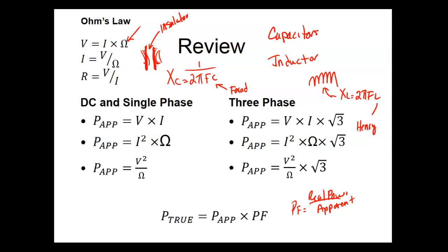Because what happens is that if you get below a power factor of like 95%, Alabama Power or TVA charges you a fee. And you think that's crazy, but their generators, their transformers, everything has got to handle the power. So it's a lot cheaper for them if you maintain a good power factor to install smaller transformers, smaller conductors, smaller generators than it is for them to compensate for you having a very poor power factor.